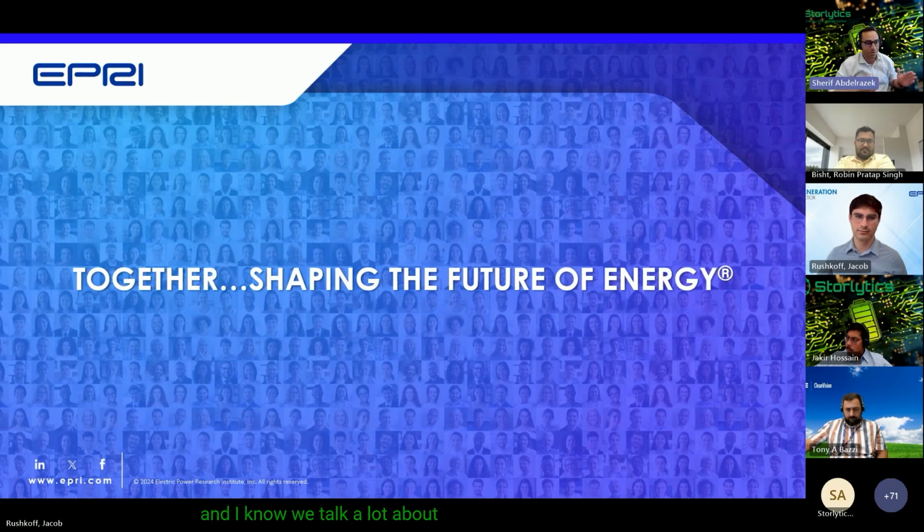And I know we talk a lot about degradation because it's important, but also the energy losses, the dispatch losses. Like if you talked about a long duration energy storage technology, if you're employing an LDES that has higher self-discharge, what's going to be the overall energy losses over the project lifetime? That really matters, and we're starting at Storlytics to see developers feel the burn of underestimated energy losses over project lifetime.